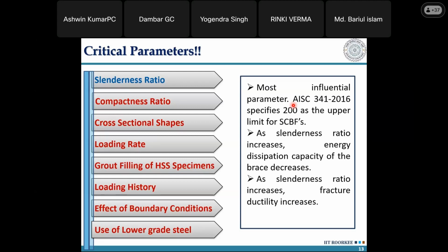If the length of the brace is of a particular length, what you might be reading, Dr. Narayan, is from that normal element, like a column element or a beam element, what is the maximum compression limit and tension limit that is given there. Look at section 12, which is where we need this element to behave like an energy dissipating element in an earthquake. So there the maximum limit in Indian code is like 165 or 160. Kindly look into the code. In US code, it is given as 200.